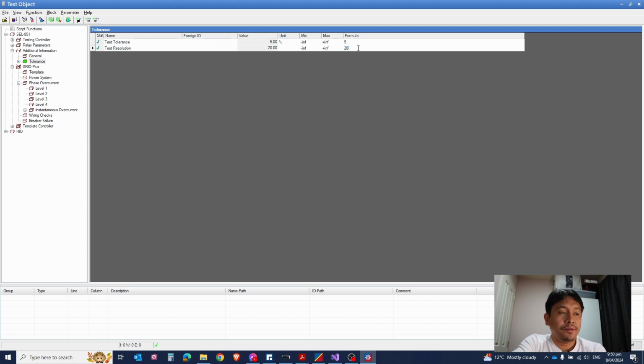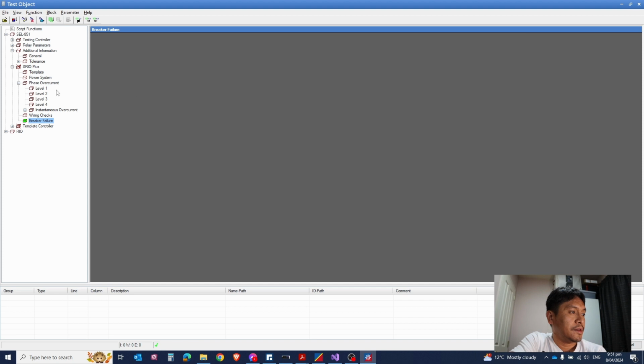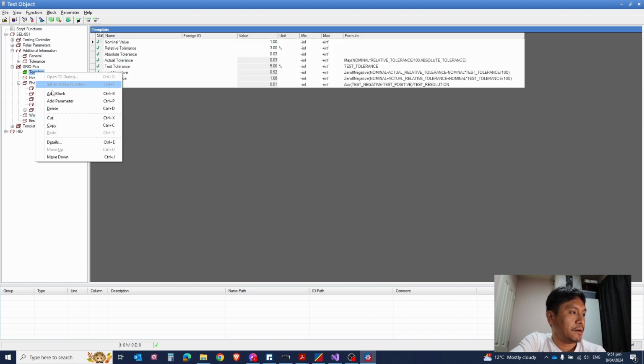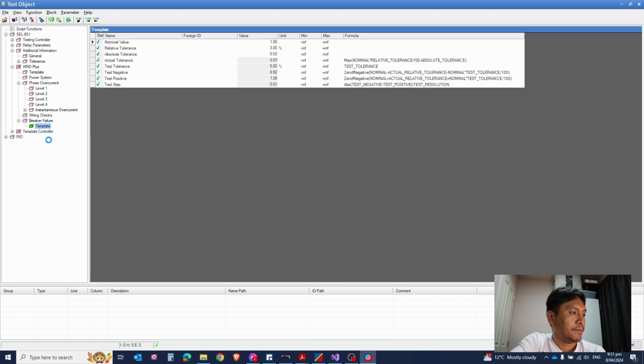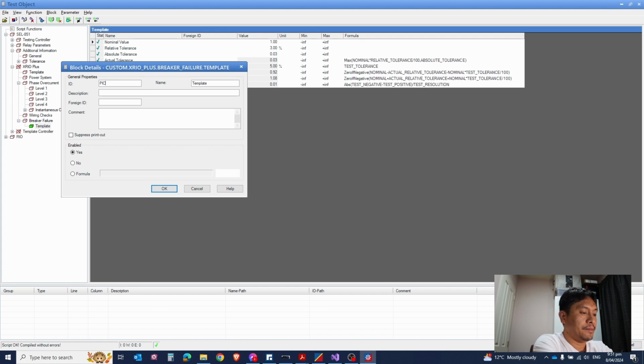So if I want to make it more accurate, I'm gonna put this higher. So let's say 30 or 50, but it will take time to complete the testing. So I'm using 20. Yeah, breaker fail. So what I'm gonna do is copy this template, copy and paste that under here, and I can rename this to pickup.